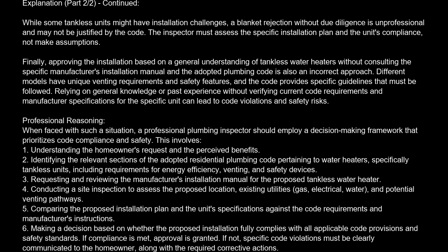3. Requesting and reviewing the manufacturer's installation manual for the proposed tankless water heater. 4. Conducting a site inspection to assess the proposed location, existing utilities (gas, electrical, water), and potential venting pathways. 5. Comparing the proposed installation plan and the unit's specifications against the code requirements and manufacturer's instructions. 6. Making a decision based on whether the proposed installation fully complies with all applicable code provisions and safety standards.